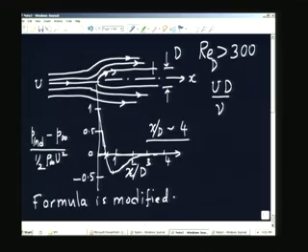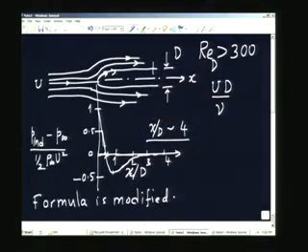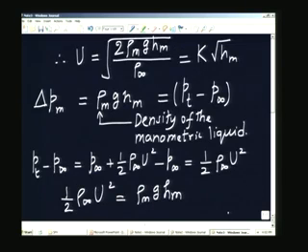Because I do not know what that is, what I will be interpreting is that the pressure difference rho m g Hm is nothing but u squared by 2, that is what we said, rho u squared by 2. No, it also contains a little bit of frictional effect. Therefore, I have to multiply the formula by a coefficient which we call C. So, if I go back to the previous slide, I will multiply this by a factor C.